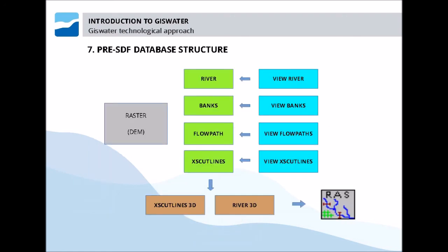We will now see the database structure of HEC-RAS. In this case, the conceptual model is completely different. While we have seen for both EPANET and EPA-SWMM that the model is two-directional, you can manage all the data within the database. The information is stored within Postgres, the mathematical model is fed, and for instance, this becomes a two-directional model.